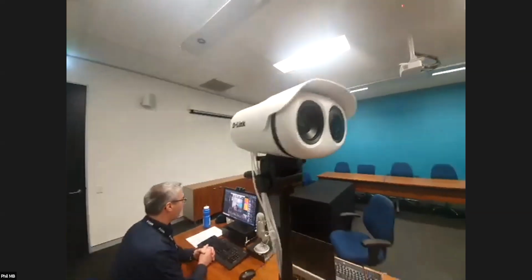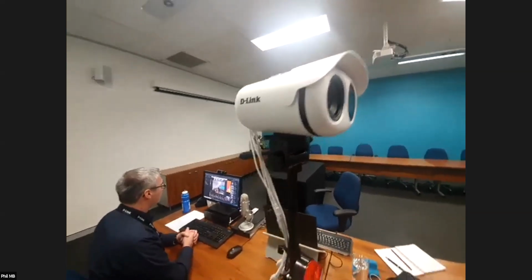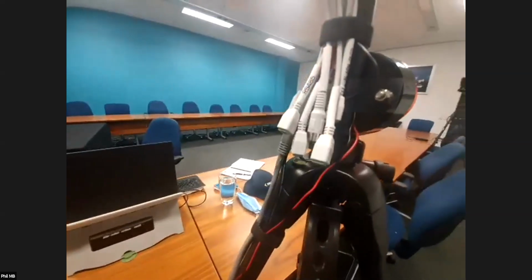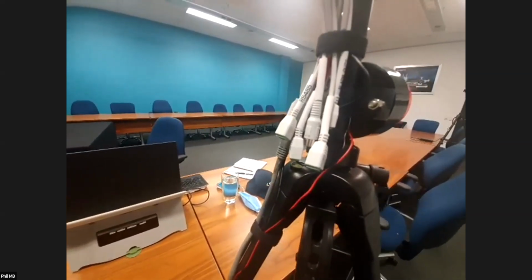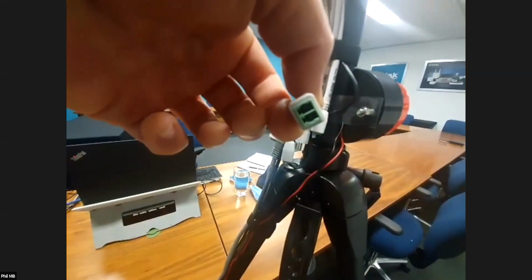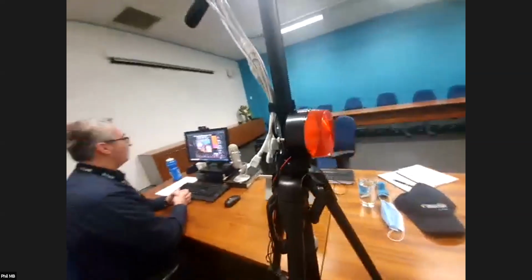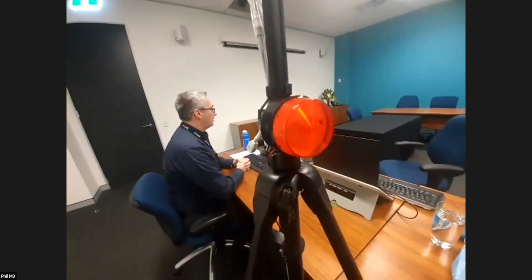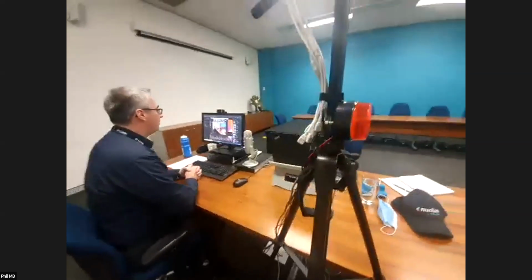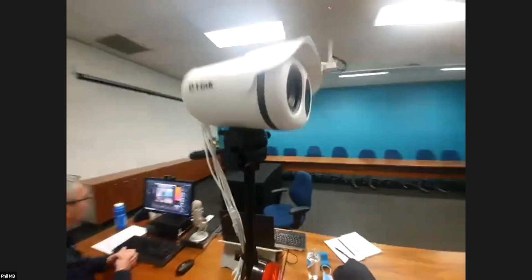The camera itself has got several connections. It can be PoE powered, but can also be powered through a regular power supply. In our case, we're just powering it through PoE, Power over Ethernet. And it has multiple connections for alarms. You can set alarm in or alarm out, like a strobe, or you can have a siren, or you can connect some other device or your alarm system. In our case, we've got a strobe connected to the camera. So when there is someone with fever or with an elevated temperature passing by, we will see that light flashing.